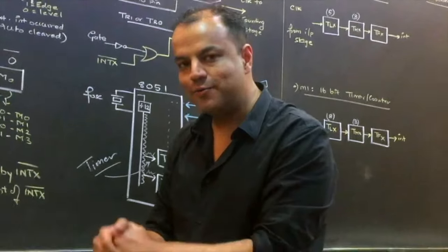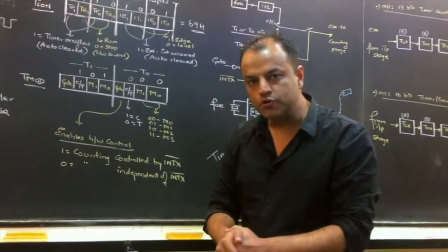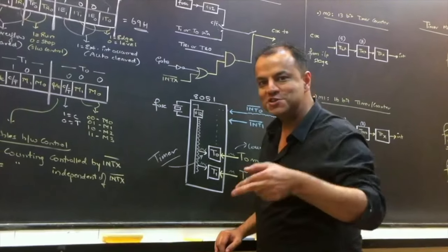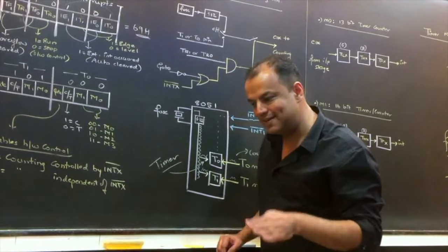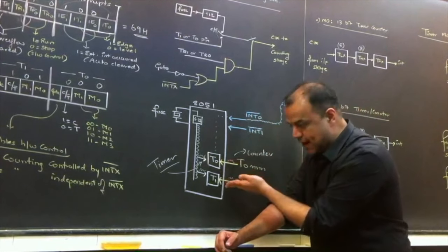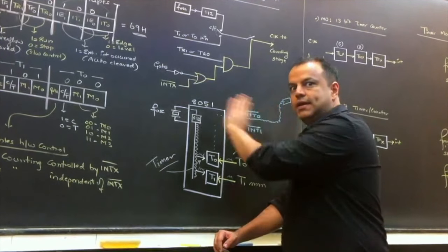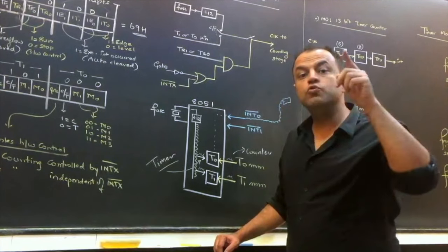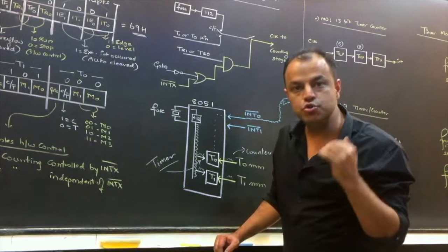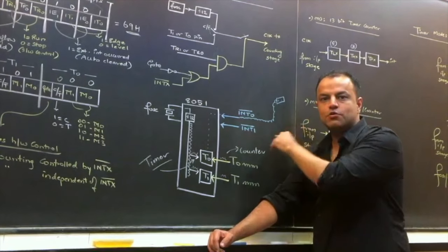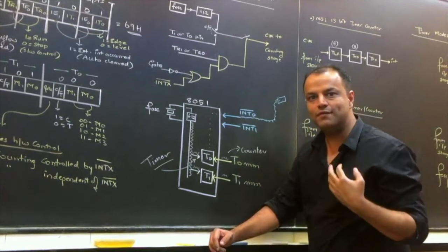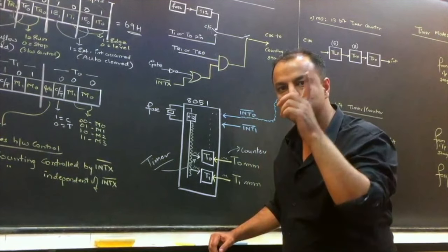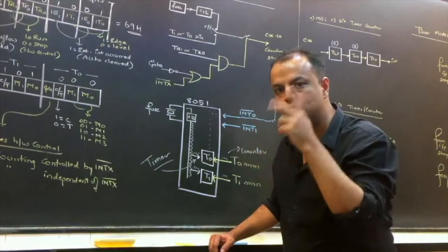You got hardware control. You lost interrupt, because the same pin cannot do two functions at the same time. Pressing a button can either start and stop the timer or be used to give an interrupt. The same pin cannot have two functions at the same time. So you as a programmer choose whether you want this feature of hardware control or not. You won't get it for free. Nothing is free. If you want it, you have to sacrifice your interrupt. The same pin cannot do two functions.